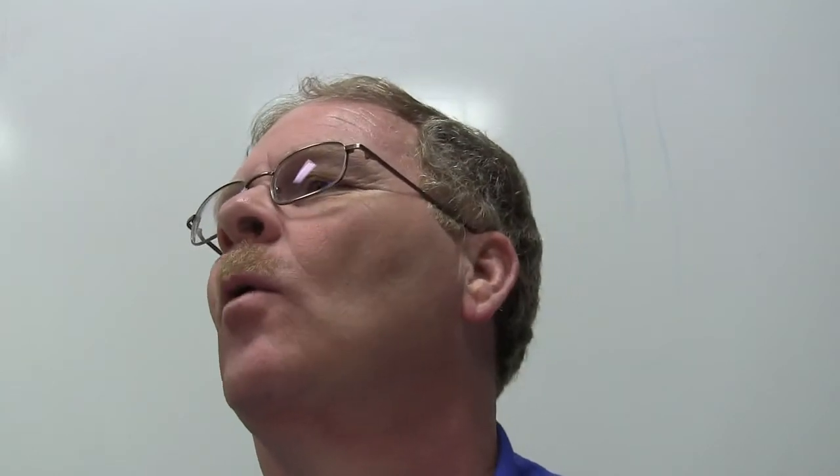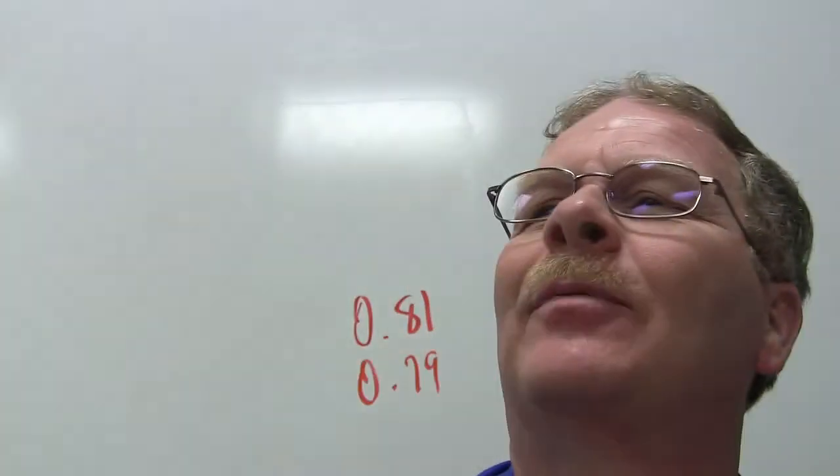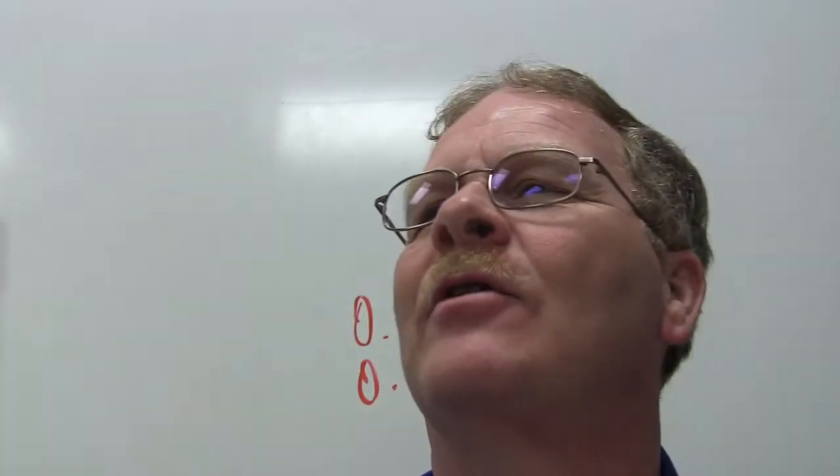Talking about the rag. Wet spark plugs. People are backing it out, pulling it in. Crank it up, back it out. Crank it up, pull it in. It's always running cold. It's always running rich. Starts to foul the plugs. And some of them, you got random misfires happening because they're not firing like they should.